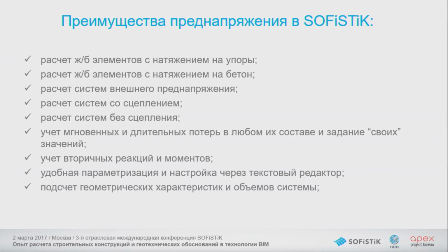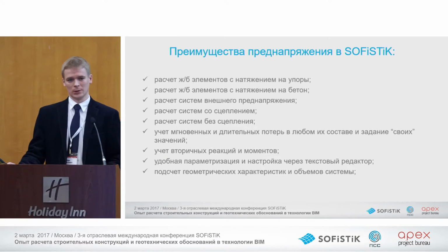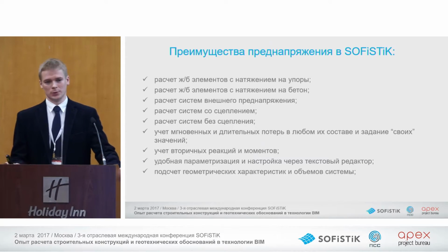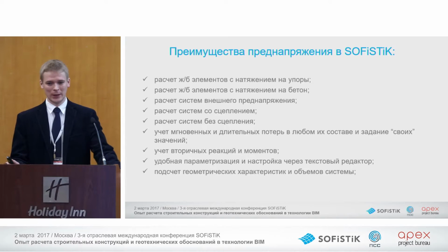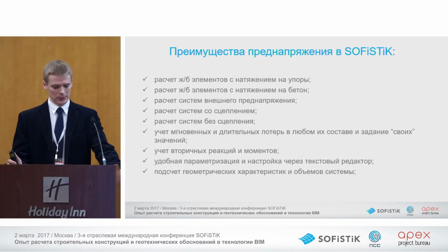And as a conclusion, advantages of pre-tension calculations in SOFiSTiK. You can calculate reinforced concrete elements with tensioning and pre-tensioning, post-tensioning. You can calculate external pre-stress systems, bonded and unbonded systems, to consider losses, time effects, and consider secondary reactions and moments.